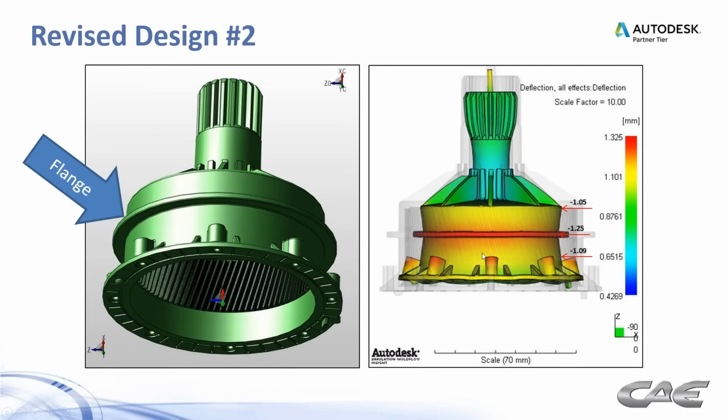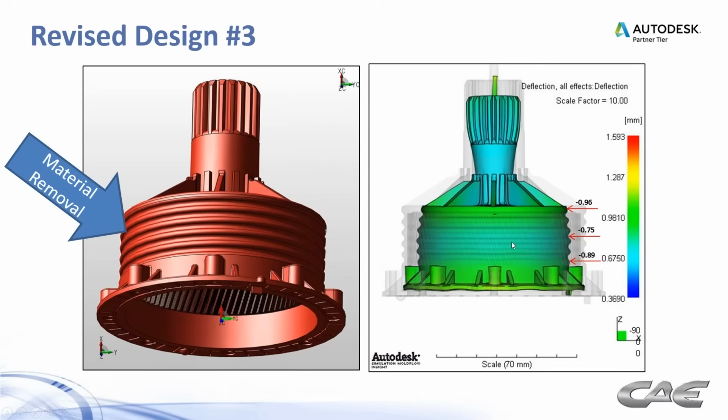This was an option presented by the OEM in this case, which would have caused some tooling issues. Same here, pretty good amount of warpage, and they actually wanted the warpage to bow outwards rather than inwards if it was going to bow in any direction. So the magnitudes here were very good, but again, a little bit more difficult to tool.